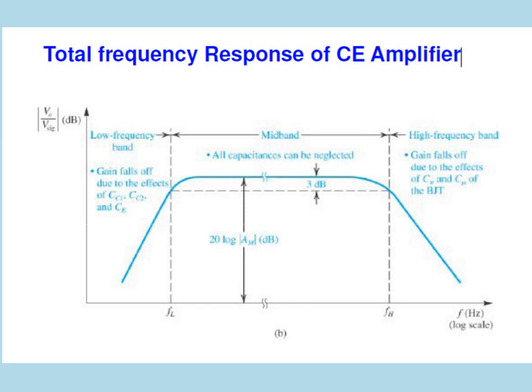In the mid band region all the capacitances are neglected, and there is a drop and increase in the gain after FH and before FL. This is due to the capacitance effect of the particular circuit. So this is about the frequency response.